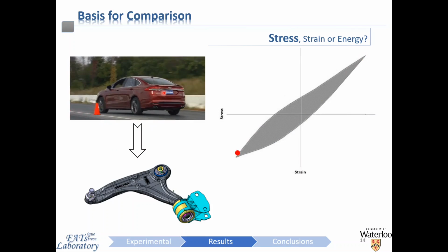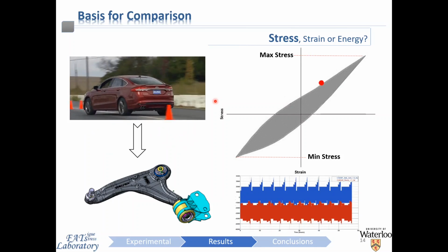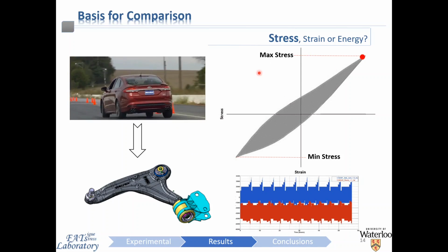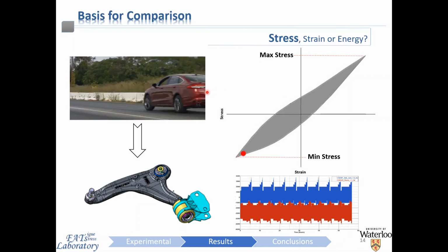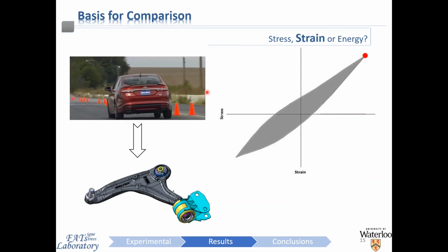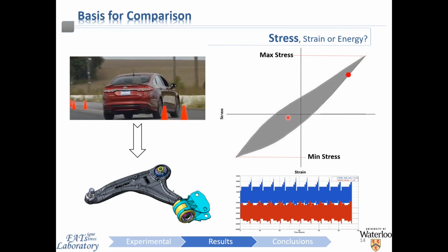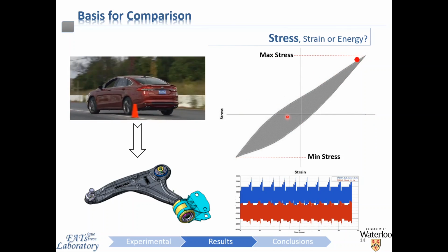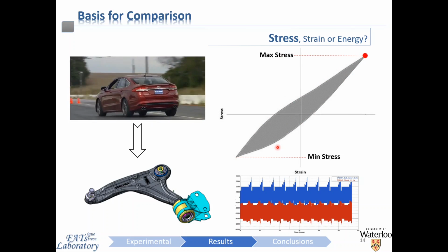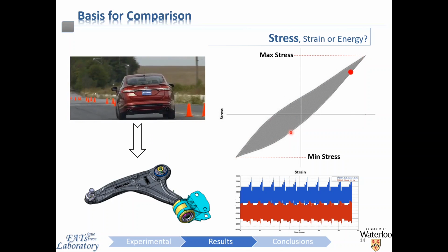As the vehicle undergoes individual cycles within the fatigue block, as we can see here, the material is undergoing cyclic hysteresis as indicated by the loop on the right here. The first approach employed is to use the stress reversal as the basis here, as indicated at the top and bottom, for characterizing the fatigue life. If we impose the minimum and maximum stresses as the boundary conditions for the experiment, then we measure the resultant material response. So the key output for this style of test is an S-N curve.